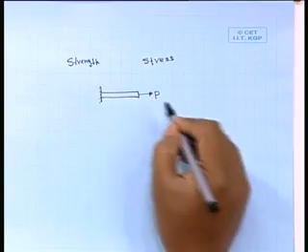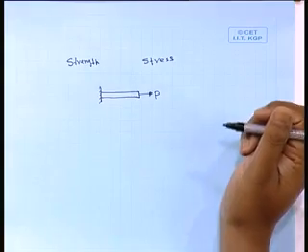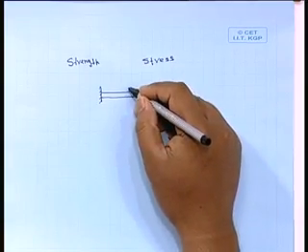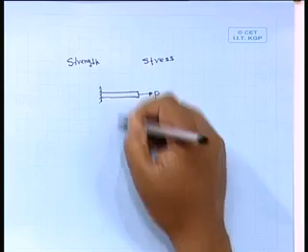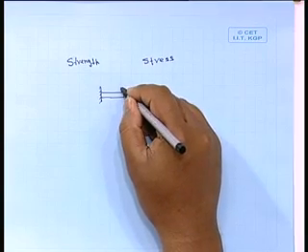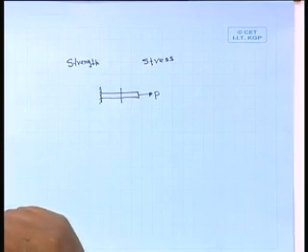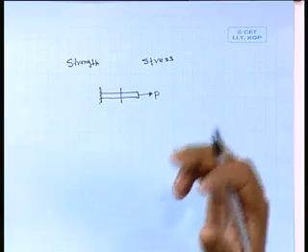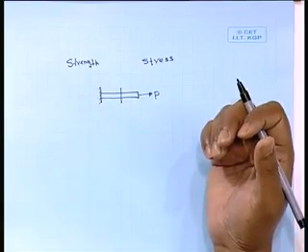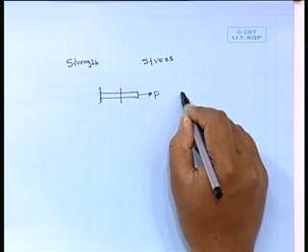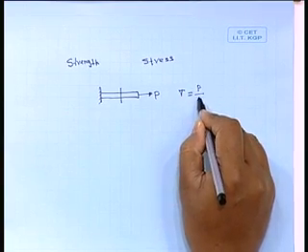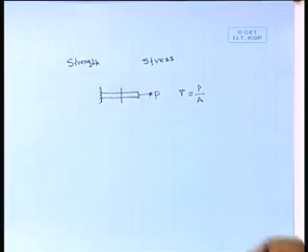So, this is a bar, and there is a load P. What will happen if we take any section, if we cut the member at any point? That P will be distributed over the entire cross sectional area. So, we define a term sigma that is equal to P divided by A, where A is the cross sectional area of that member.